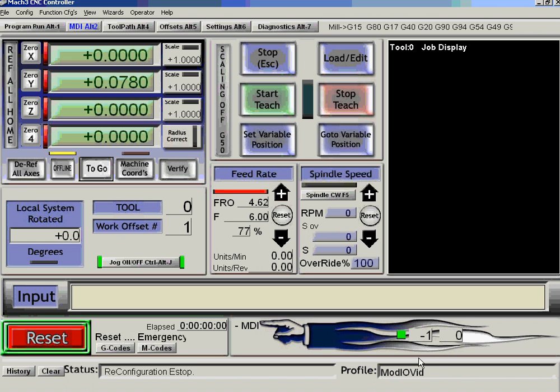If we take the power off, we get an error. Now it's config number 3 which is causing us problems. That's just because it was the first one that was scanned, I guess. And the error code is 9, which means timeout. If we put the power back on, Modbus protocol recovers. So no error, and -1 for the error line that's referred to. So that is a way of looking at the status of the Modbus devices during normal running.